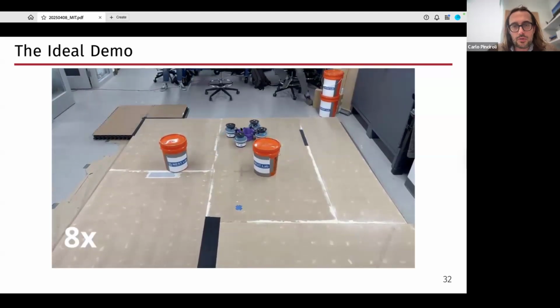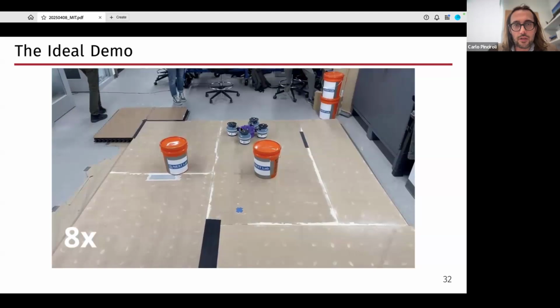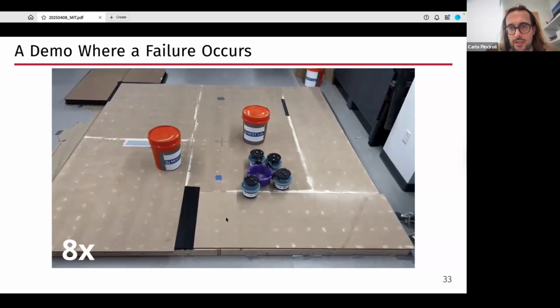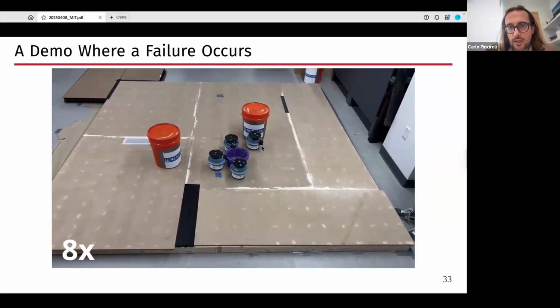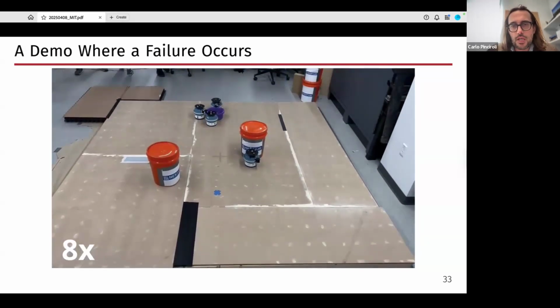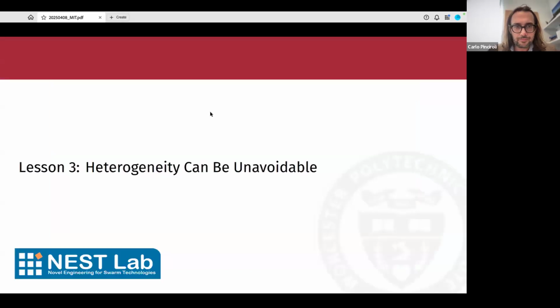One thing that was interesting to us is that we got lots of failures. In particular, these robots had a problem here. One of the grippers failed. And so the other 3 robots, with the neighbor's version of it, were able to ignore the fact that one of the robots was lost and adapt to the fact that only 3 robots were left, which is nice. Again, it's one of the properties of just talking to your friends immediately left and right of you, as opposed to having to talk to everybody and not receiving certain messages that you're expecting to receive.